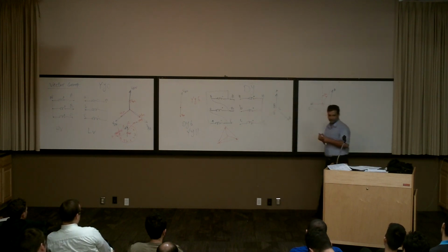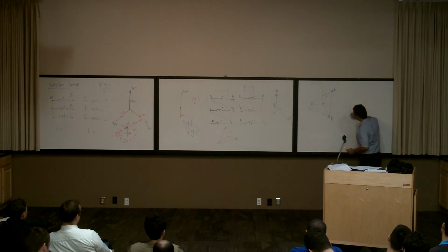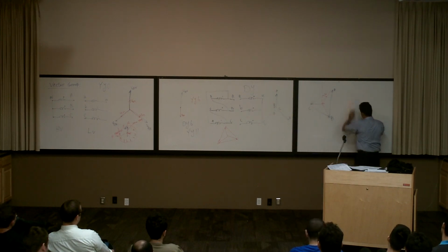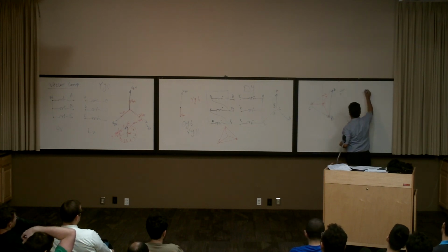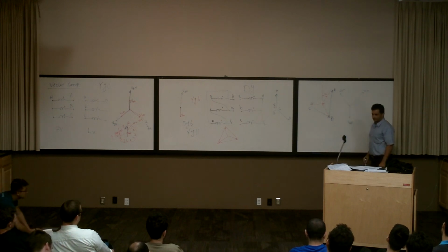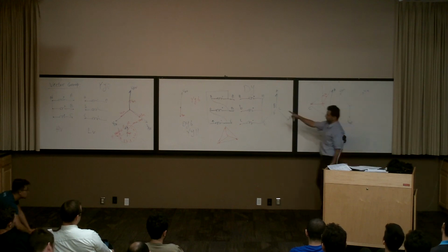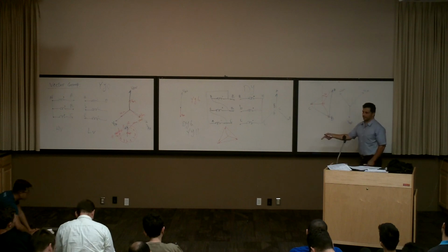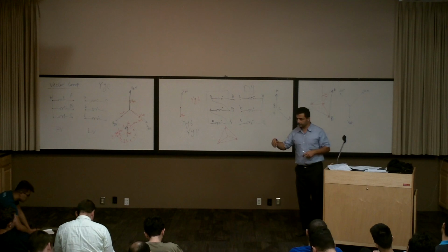Now let's draw the other side. This one was easily settled. So basically, it's going to be like this: VAN, because the dot is here, then VBN and VCN. Correct or not? If the dot was up here, it would be VAN, VBN, VCN. Because the dot is on the other side, I just rotate them 180 degrees.